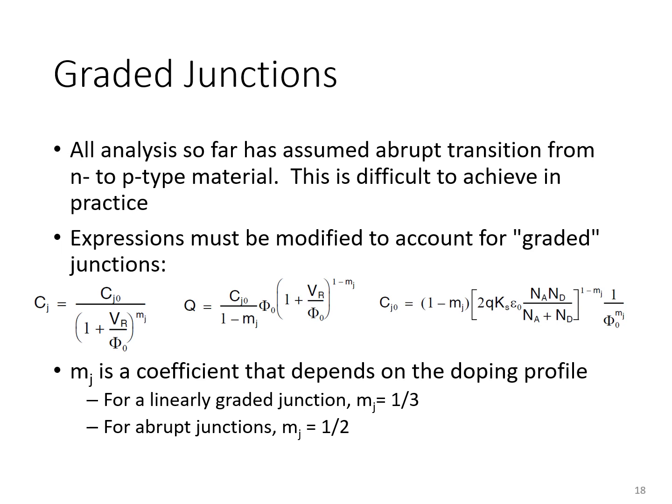So in practice, as you can imagine, the dopant concentrations don't change abruptly with one atomic layer of thickness. There's a gradual transition, and the result is that this exponent in the model of capacitance deviates from -1/2 to more like -1/3, depending on the specific dopant concentration profile.